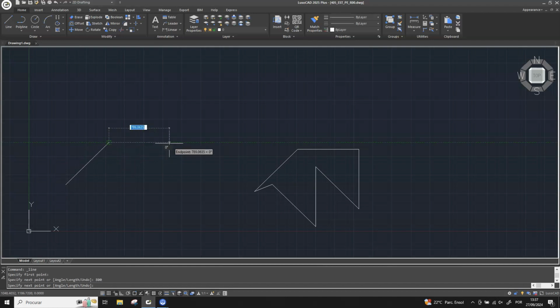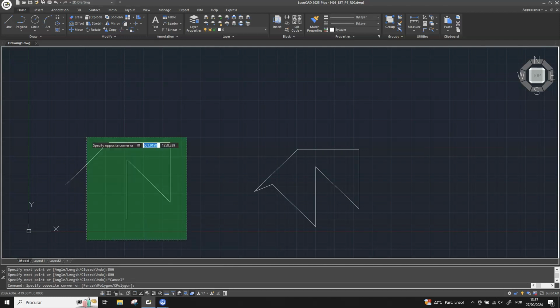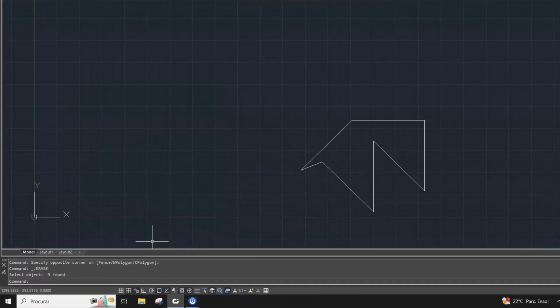If we try to draw normally, we can actually get it correctly. But as you can see, the process is quite tedious while getting the right angle with the mouse. It would be very useful for us to give priority to the angles with increments of 45 for this specific drawing. This is exactly what Polar Tracking offers us.